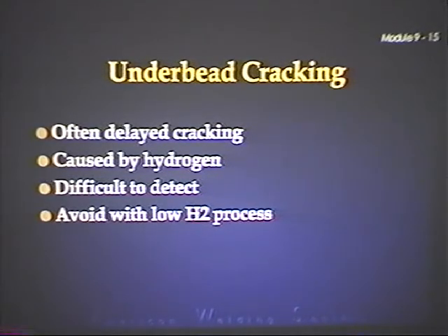You're using low hydrogen electrodes like 7018, but to stay within the code on using low hydrogen electrodes, you've got to make sure that they've been heat stabilized. You take them out of the rod oven, you use them. You don't leave them exposed to the air for more than 6 hours, well actually for more than 4 hours, depending on the moisture, atmospheric moisture and so forth. So you've got to maintain that quality control.